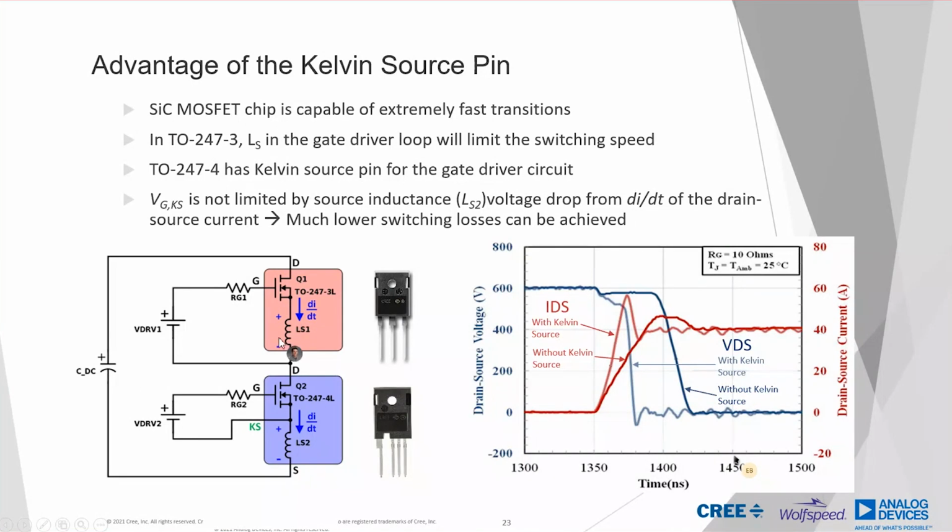So you get this voltage drop across the source pin. That's actually going to act to subtract off your gate drive voltage, since your gate drive is connected outside of that inductance. And so that's going to slow down the turn on event and therefore increase losses.